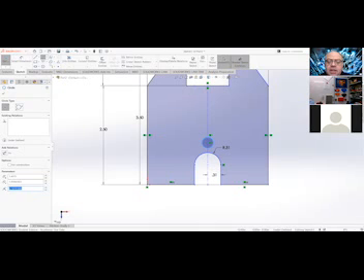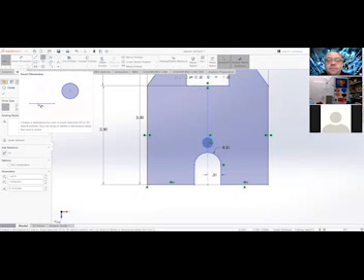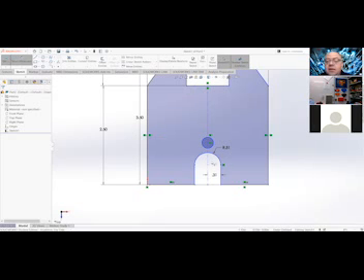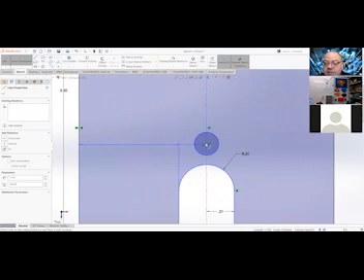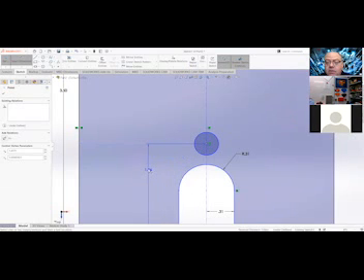Really quick and easy. And our distance on there was 1.06, and the circle was 0.255 in size. So we're going to use Smart Dimension. Yay, Smart Dimension. First, I'm going to pick the horizontal line. I've got two now, doesn't matter which. And I want the center of that circle. I want that nice orange dot. Oh man, am I good at what I do?